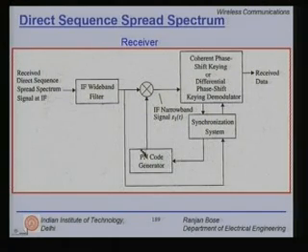Now, you should have the same code that was used to spread the message signal to despread it. If you use the same code, you despread your signal. If you use a wrong code, then you spread it further. You multiply it. The moment you despread it, the bandwidth reduces and now it is an IF narrowband signal. Now, you can do detection and obtain the received data.